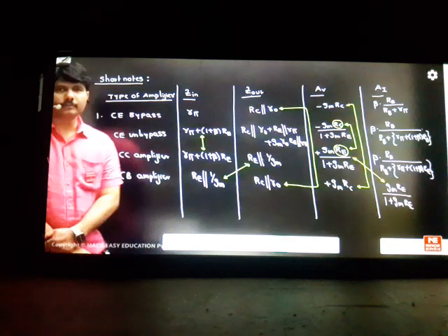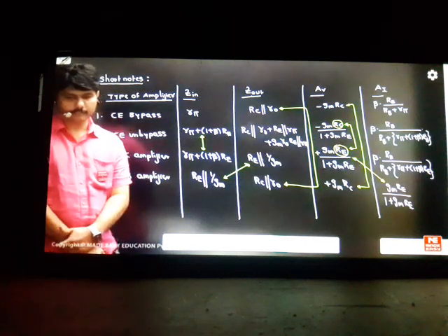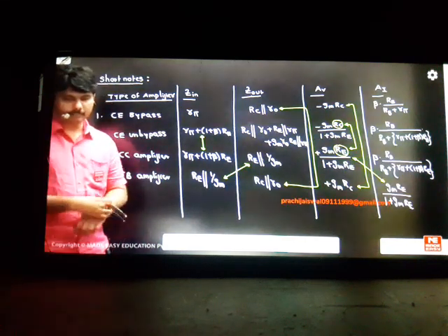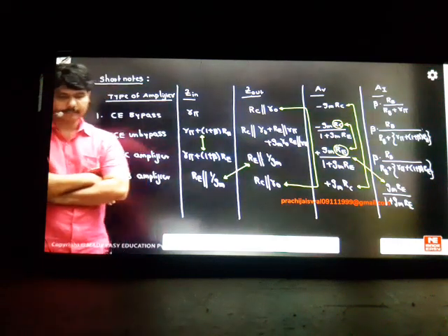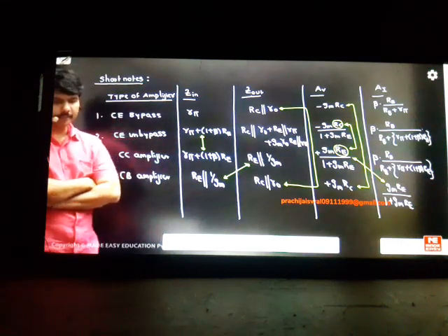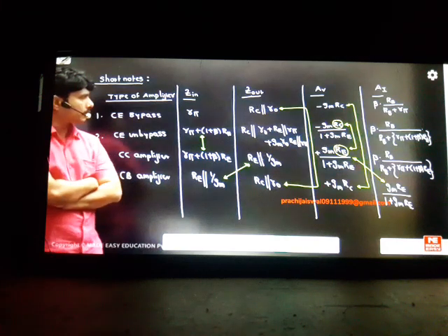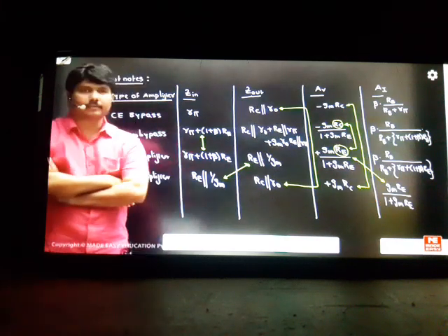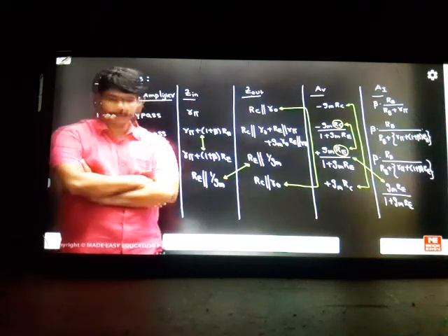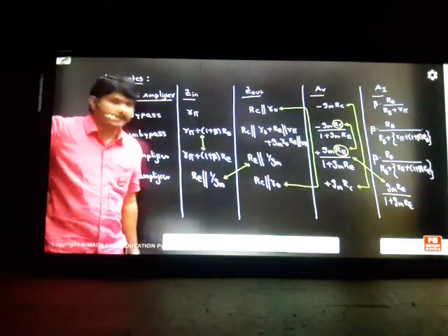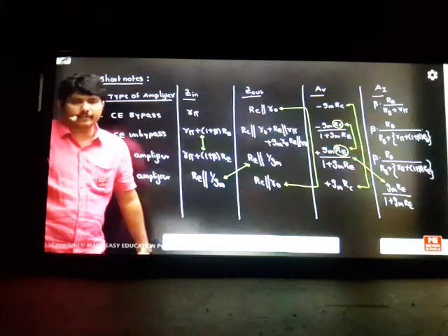Let us find out the solutions of the 4 questions. When you are practicing amplifiers, just have this type of knowledge, then you can do whatever you want. Visualize the formulas from the diagrams; they should be in your imagination. Then only you can draw the total formulas. Whenever I say common emitter, that should come into your imagination. Common emitter bypass, Re will not be there, so R pi is the input impedance. Like that you have to visualize the formulas. Take a white paper, first practice the formulas and circuits, then shortcut methods will automatically be remembered. But practice is required, nothing more than that.